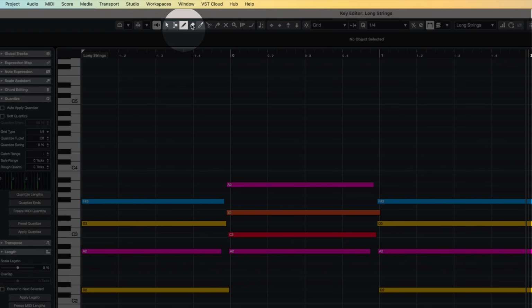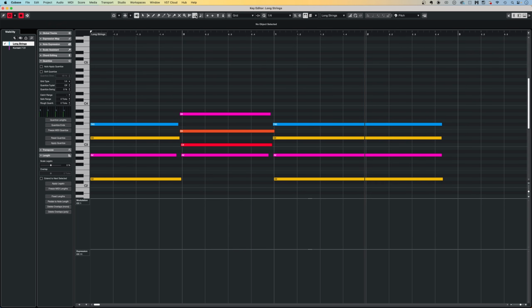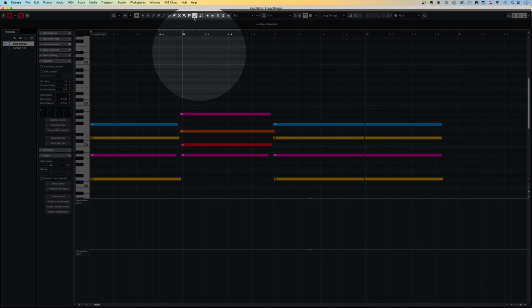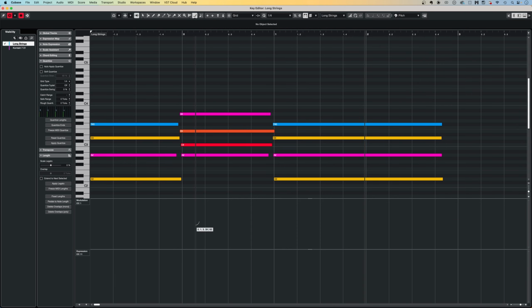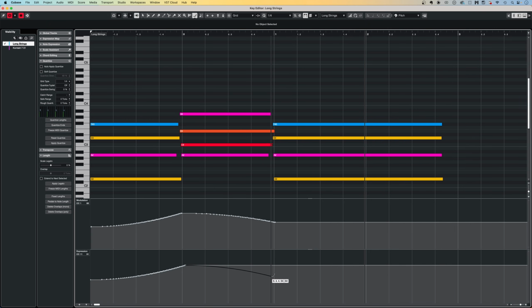Then select the pencil tool, again using the shortcut 8 to draw in the data freehand. For a more refined shape, like a smooth curve, head over to the line tool and then click and hold, until you see options such as the parabola. Now you can draw in smooth natural dynamic curves by clicking to the left and then dragging over to the right.